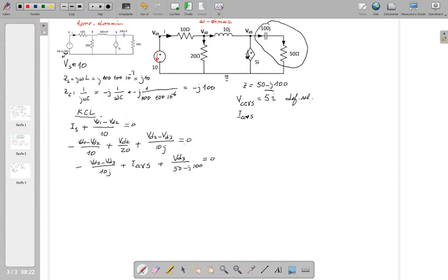If you count now the number of unknowns, one new unknown came in, this is another unknown, IS, we don't know that, and the other unknowns are VD1, VD2 and VD3. So altogether we've got 5 unknowns, but we've got 3 equations here.